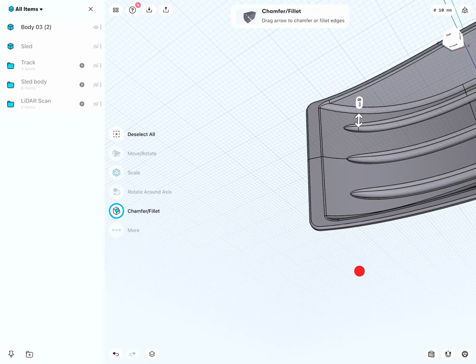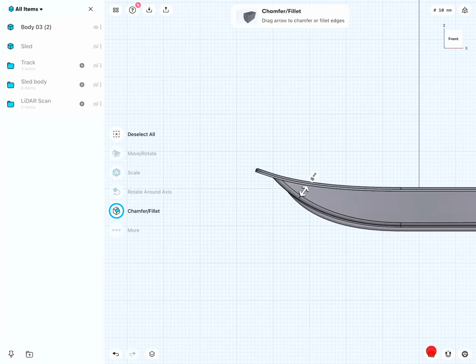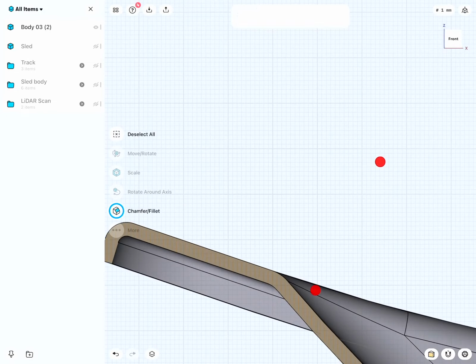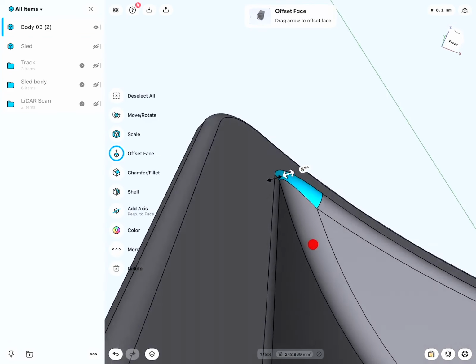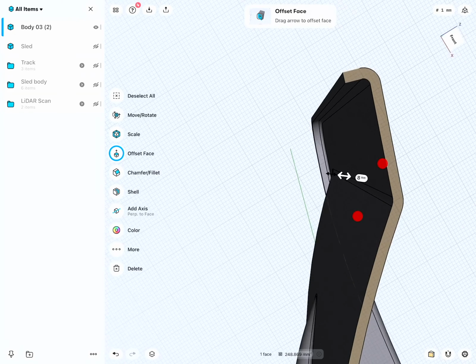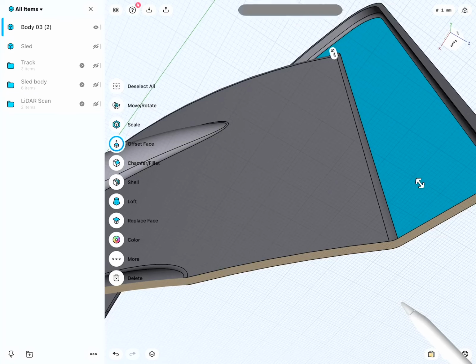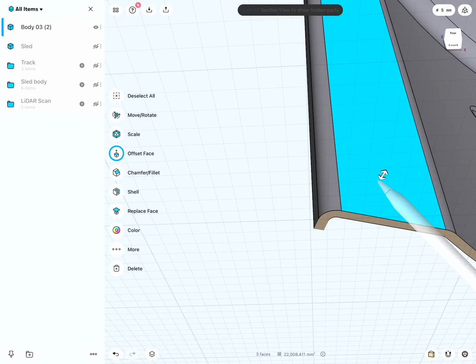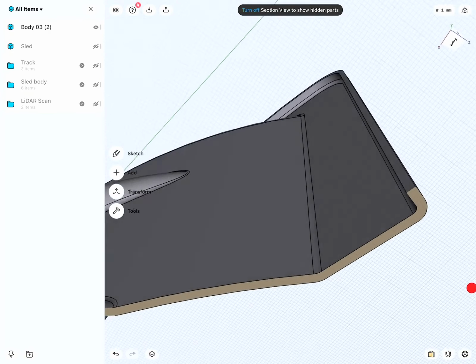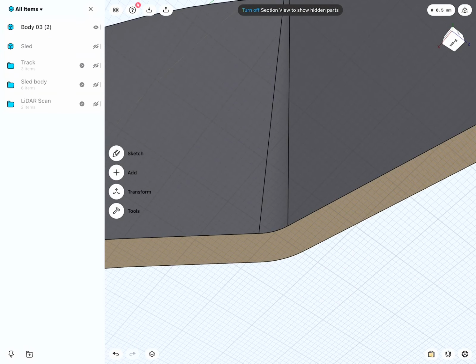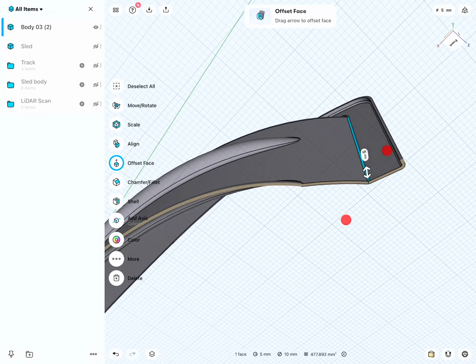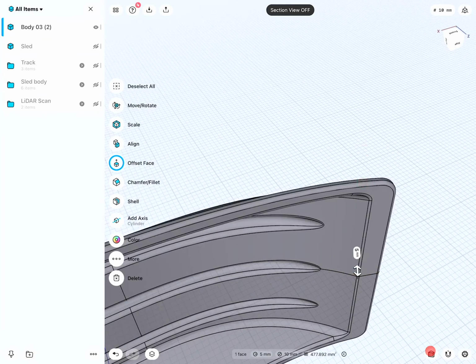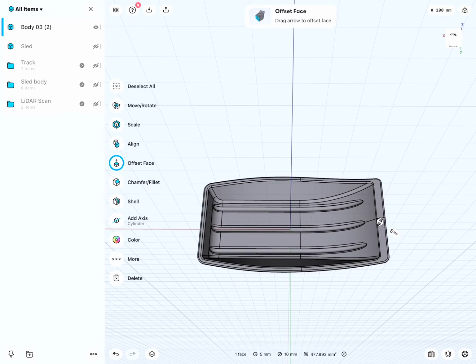The reason why I'm calculating inside and outside radius is, now you need to keep in mind, when this is the outside radius plus the material thickness, which is 3, or in this case, outside radius minus material thickness, will result into the inner radius. So that's the reason why I did this calculation.